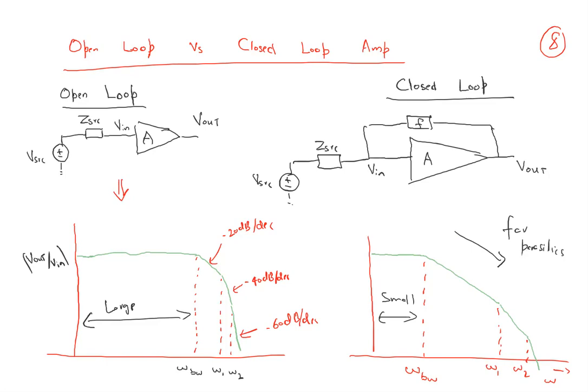Because in your system, the dominant pole is going to be mainly the factor for bandwidth. If they are far, it's very good. So we want them to be far. Why do we want them to be far? So that the system is stable. Every pole counts for minus 90 degrees, and we know that the farther they are, the better it is. So in open loop, in general, we want all the limiting poles to be as high in frequency as possible, but in closed loop, we want the pole deciding our bandwidth to be as far apart as possible from the non-dominant pole.